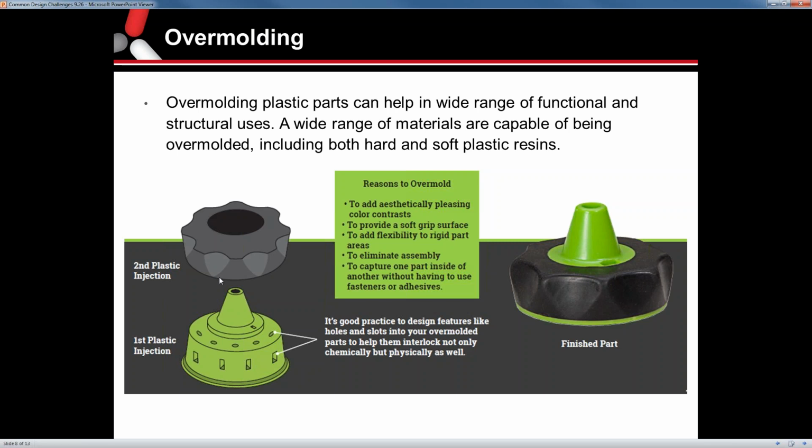Often we run into, if we're overmolding a metal piece, the tolerances may not be super tight. When we're dealing with a precision mold, we need to make sure that those are very consistent, not only part to part, but lot to lot, because you don't want to be changing and modifying your mold each run to basically fit that insert, because that will affect shutoffs, flashing, and all that. So just having consistent inserts that are being overmolded.